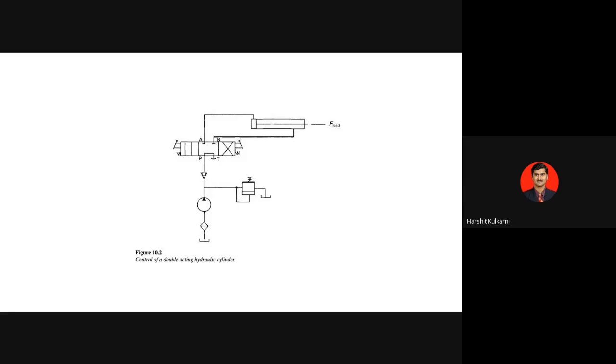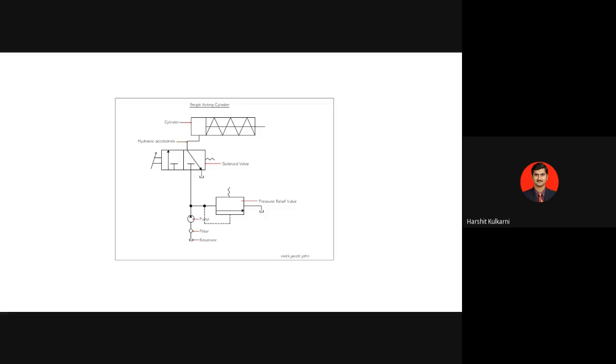Similarly, if you go to the earlier case where you had a 3x2 position valve, there I can drill one more port and make it the B port, or instead of drilling, maybe it was already a 4 by 2 valve. We have just blocked the B port. I'll open that block, then it becomes 4 by 2. Single acting, in this there is no B port.